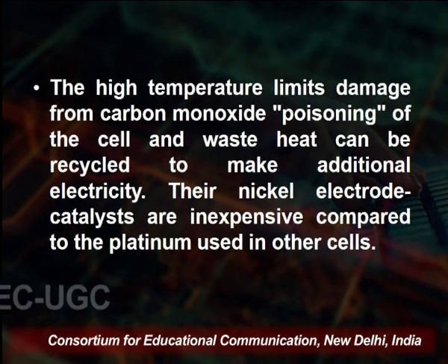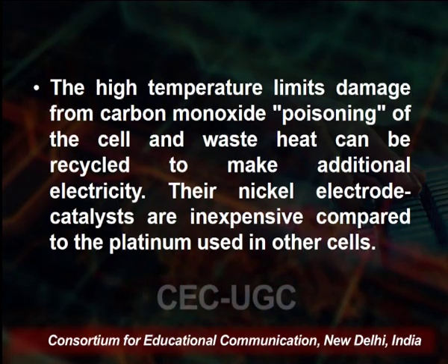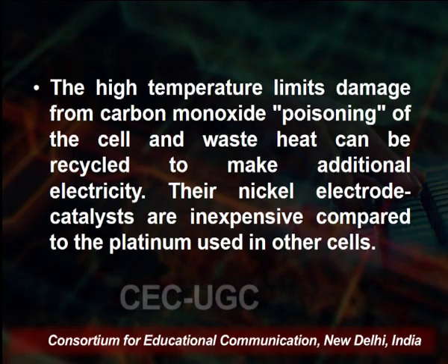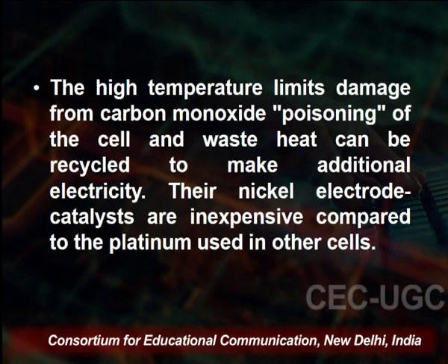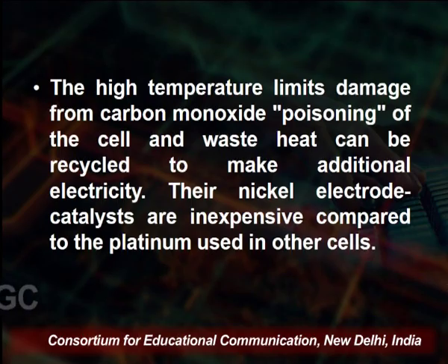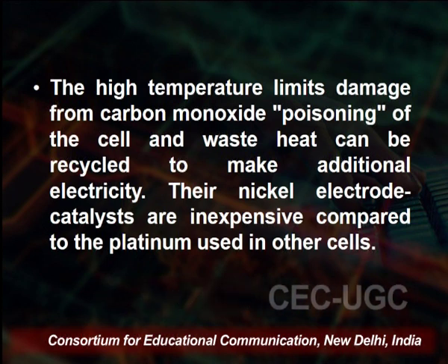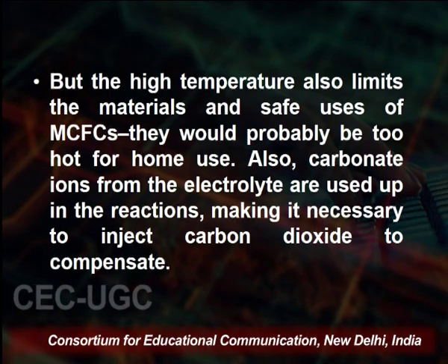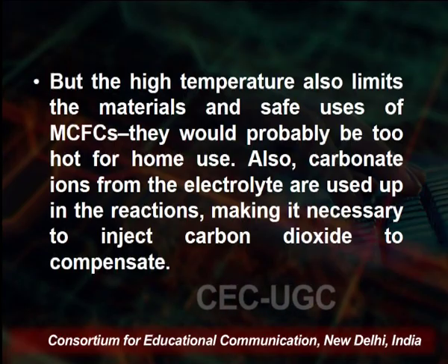Now, the high temperature limits the damage from carbon monoxide poisoning of the cell, and waste heat can be recycled to make additional electricity. Their nickel electrode catalysts are inexpensive compared to the platinum used in other cells. So, in this cell we use nickel electrodes. Moreover, there is a combustion of the carbon monoxide inside the cell. However, the high temperature also limits the material and the safe use of the MCFC.